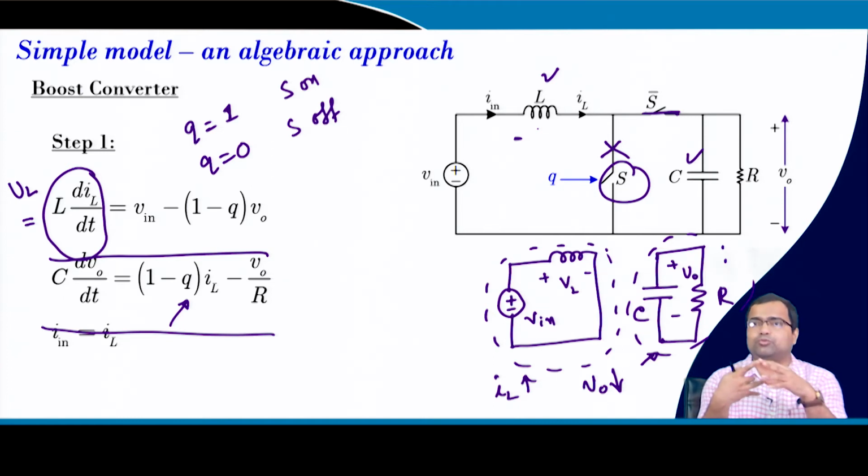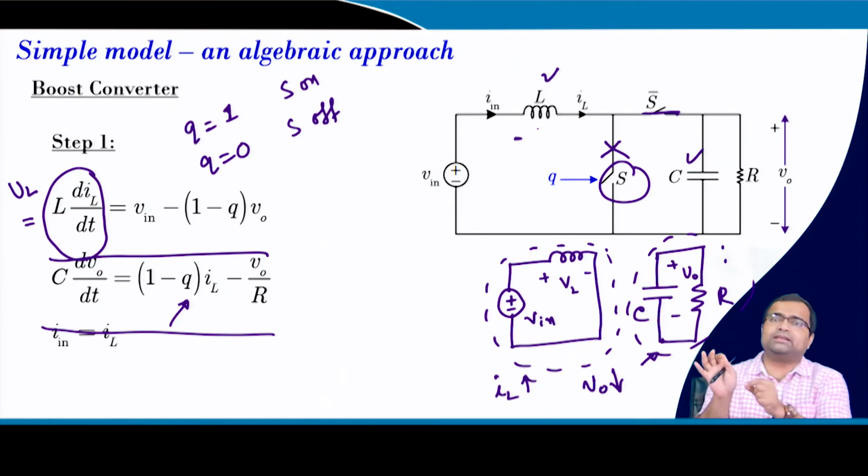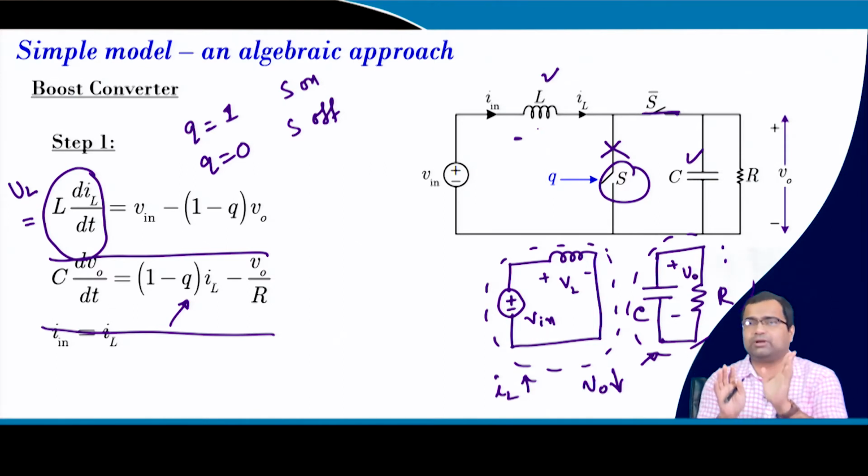In that case we need to put a capacitor, because the solar panel should not be exposed to the discontinuous current. But in case of battery charging or LED driving, where on the load side we need a continuous current, we generally apply a buck derived topology, where the inductor is in the output side.